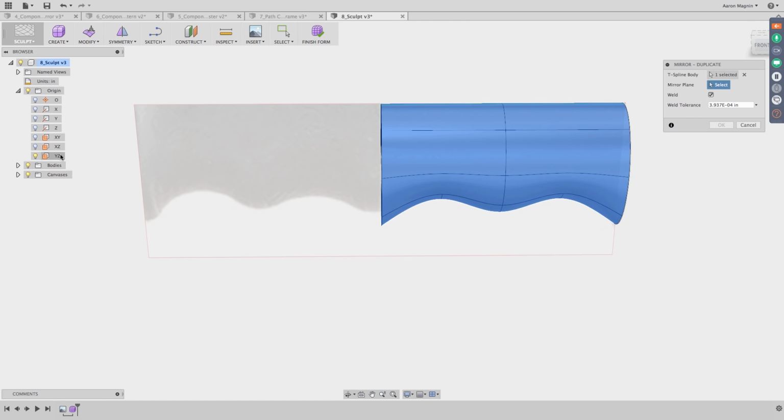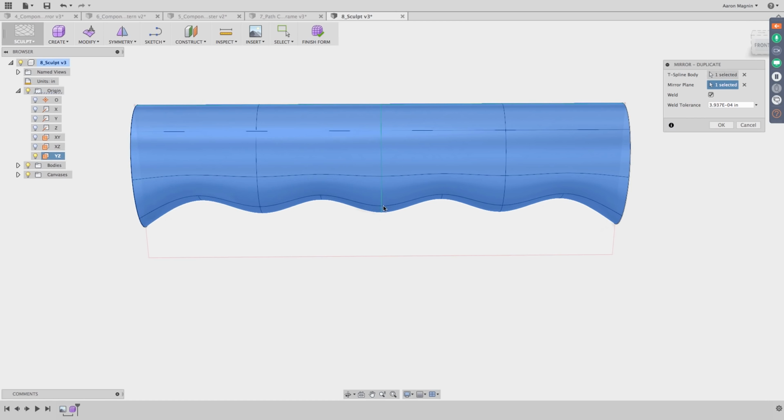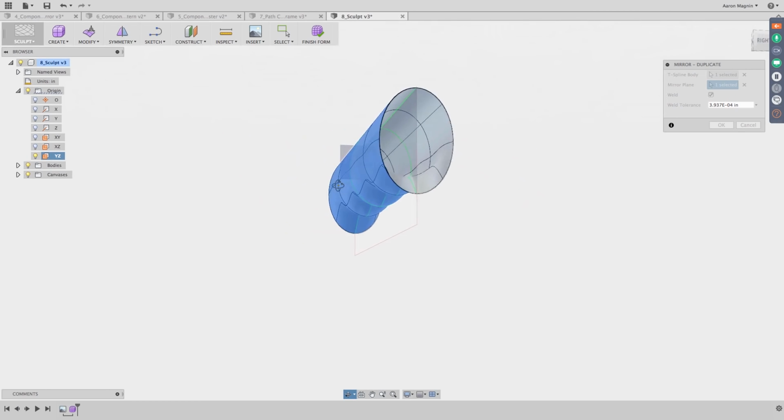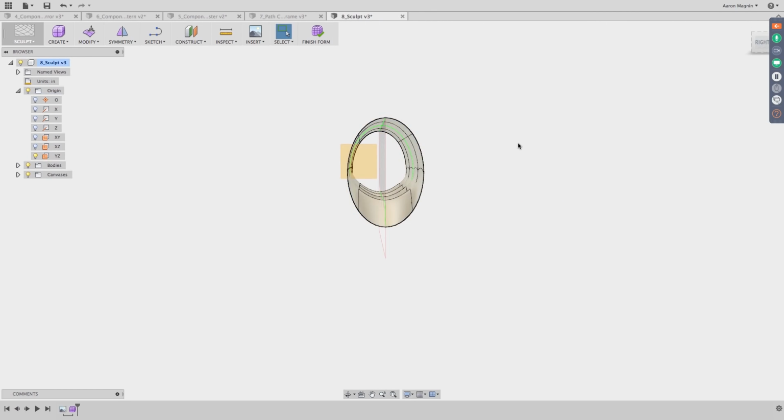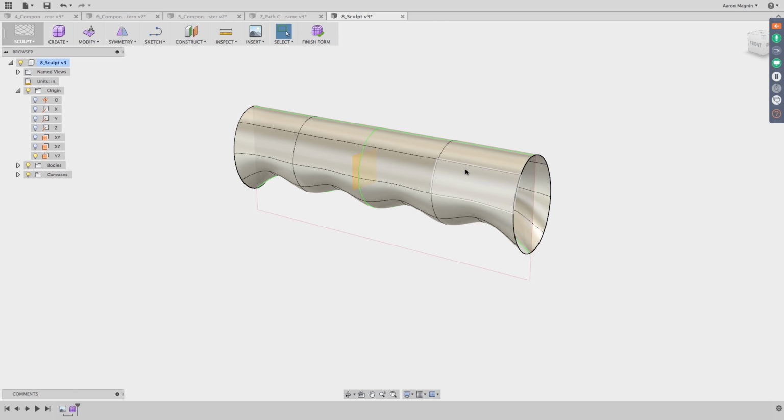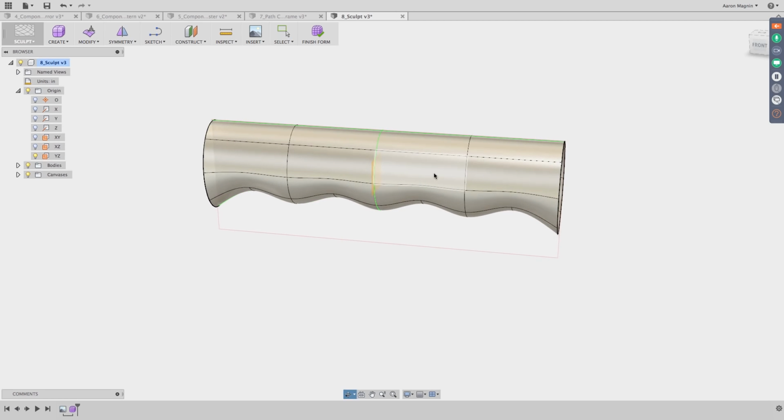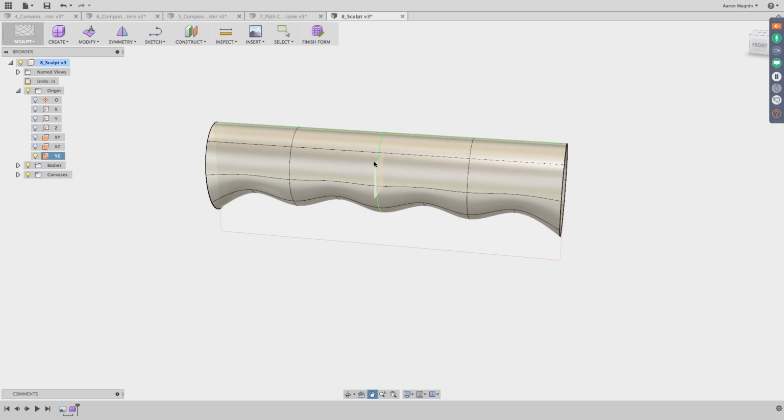So again, as I select that mirror plane, it finds that additional face that it's attaching to, and it actually adds that roundedness to this to ensure that curvature continuous is always going to be present. So just like that, we can go ahead and click OK, and we're really happy with the way it looks. It actually adds symmetry to either side, and obviously when you do that in your duplicate, you do want that to some extent. But sometimes you want to actually remove symmetry, right?